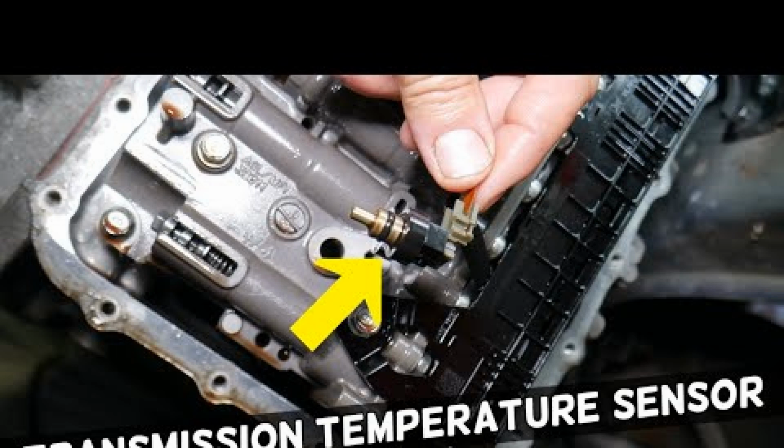Transmission temperature sensor test. Test the transmission temperature sensor to assess its performance. Use a multimeter to measure the sensor's internal resistance at various temperatures. Compare these measurements with the manufacturer's specifications to determine whether the sensor is operating correctly.